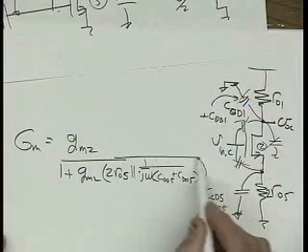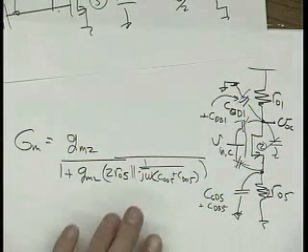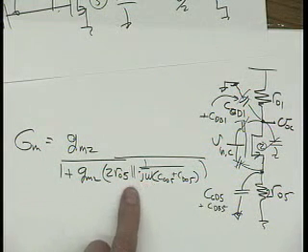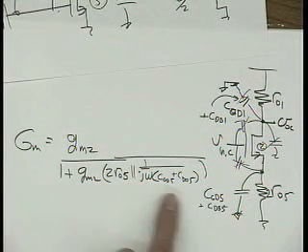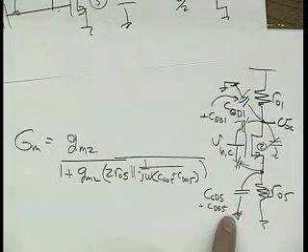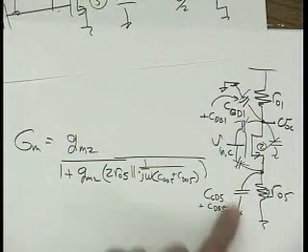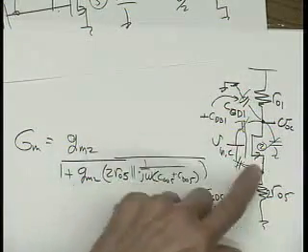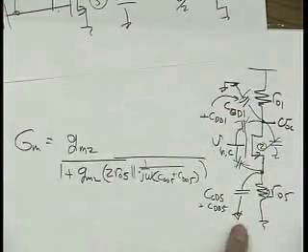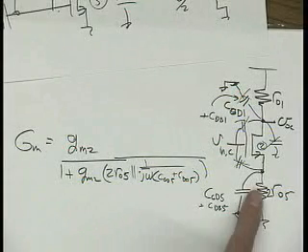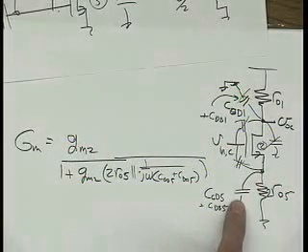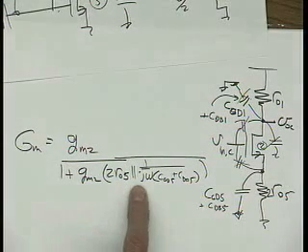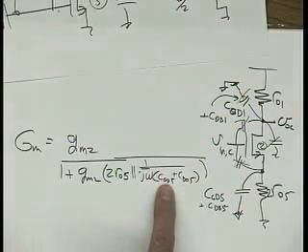So this is another way you can solve these things. You just take the low frequency gain formula, and it shows you what's going to go on. I look and see where I have some extra impedances changing that result. And this CGS does something very different, because it's kind of coupling between the gate and source, so you have to handle that much more carefully. But right here, this capacitor is just in parallel with this resistor. So this resistor is in parallel with this set of capacitors.